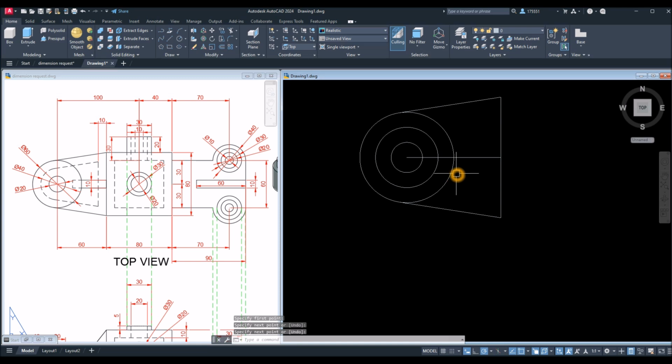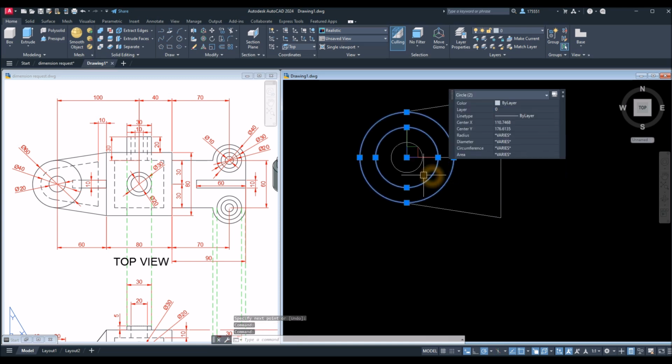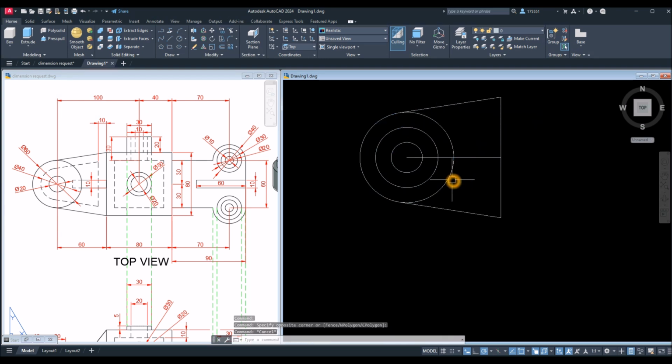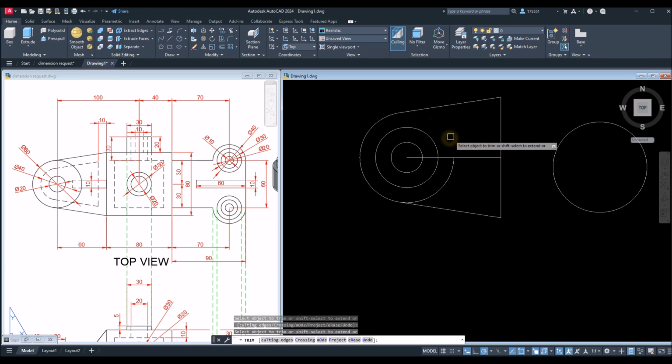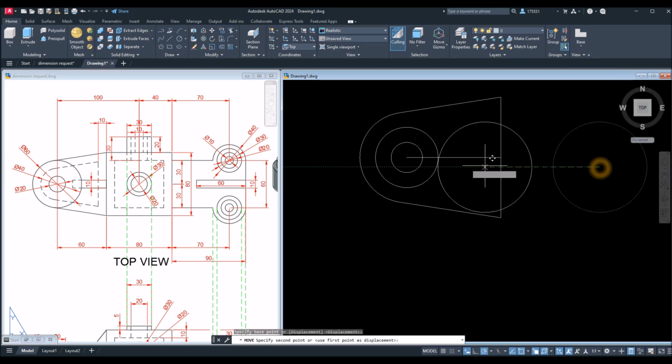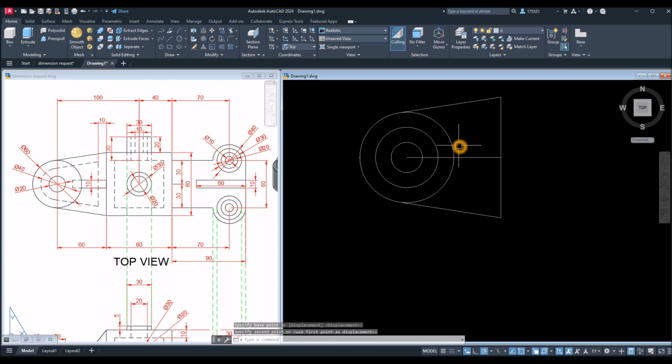Now, I'm gonna copy these ones first because, no, just this one. Copy. I need that later. All right, and trim. Enter twice and trim that. Trim this one and join the segments. So J for join command. Join these segments, that and that. Now I need that later to extrude. So move this one back and snap the endpoint.